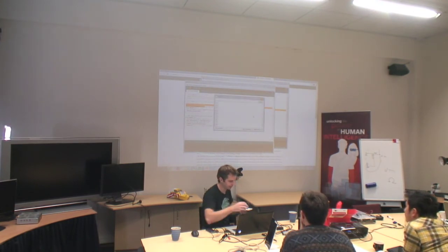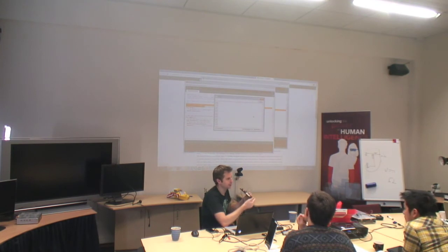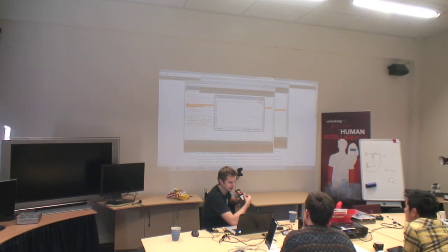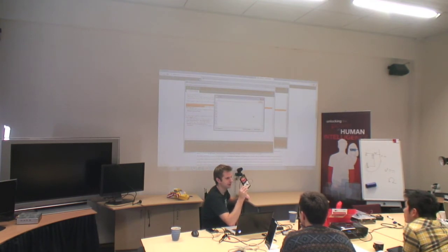And so yeah, this is reading 1023. If you remember, it's a 10-bit thing, so I can go from 0 to 1024, and as I turn this around, once I figure out which direction it goes, it will gradually decrease until we hit 0 volts. So now we can basically measure how far around this has been turned. If I put it roughly in the middle, it should be 512, somewhere around there.